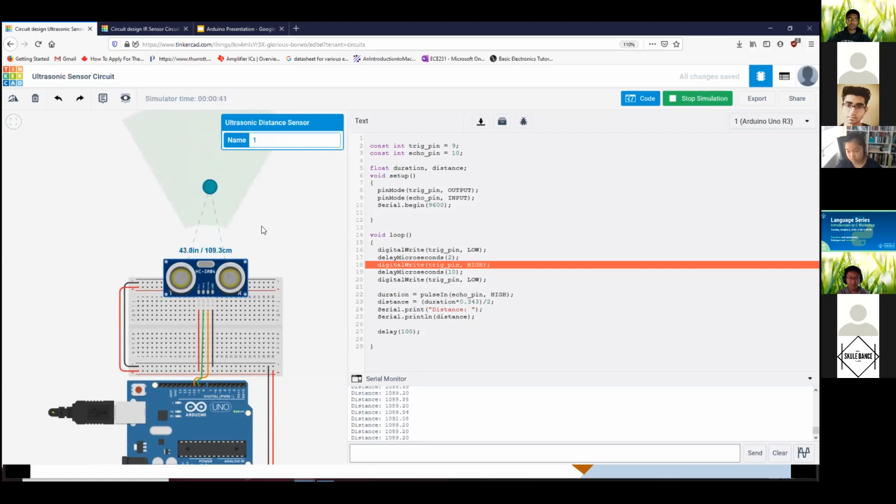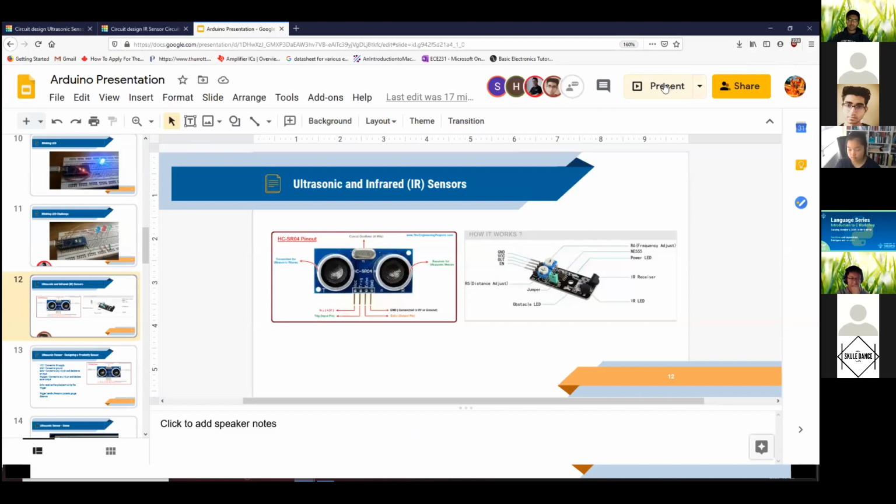Okay, perfect. Now, one thing to note is if I bring it outside of its range, it's going to read very bad, like basically garbage numbers. The reason is the trigger pin works on an intersect of the waves, because there are two pulses being sent out. If you do not land within those intersections, you can't get a reading. That's why outside of here you don't get a range, you don't get a number. So that being said, we'll go back to our presentation.